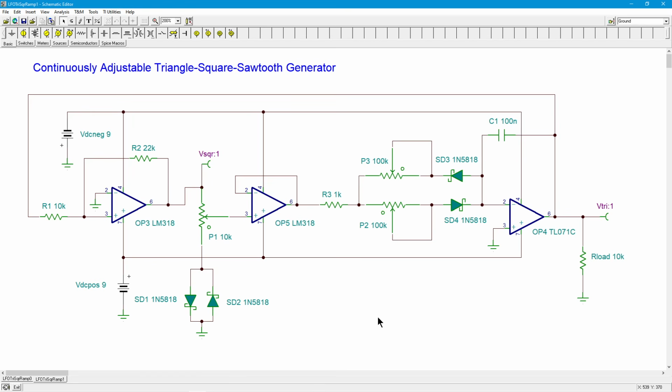Bingo. I'll explain this in just a moment. But first, before I do, I want you to right now ignore this stuff right in here. This is really here for like accuracy and something we're going to get to in just a sec. So just ignore this pot, these Schottky diodes, and this little op-amp buffer. This is only a high input impedance, low output impedance, voltage gain of 1. Just ignore this. Just pretend that this point right here is going directly to R3.